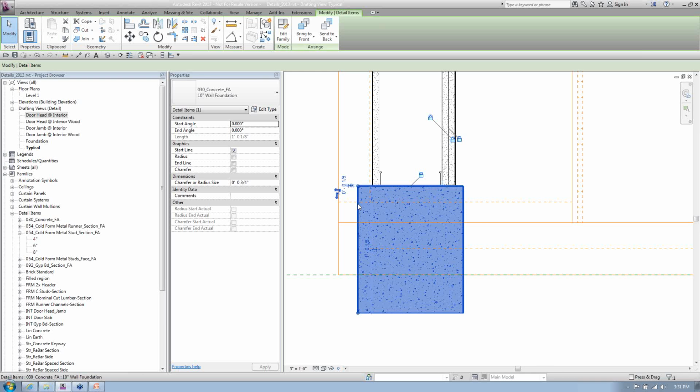You absolutely can do that. I highly recommend against doing it. If you've got a hybrid detail where you've got components over it, go to the detail, you'll see the model behind it, you'll see it updated. I don't think it's that big of a deal to go through and adjust it. Yeah. Plus, the problem that I always have is somebody's going to align and lock 10 of the objects but forget 2.